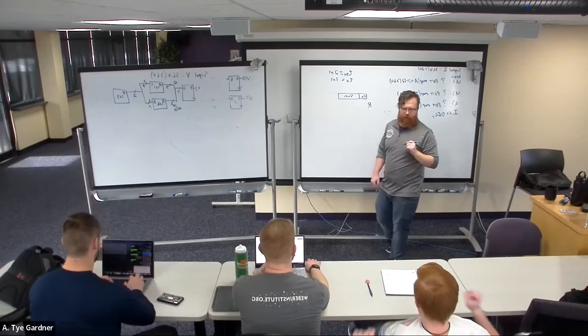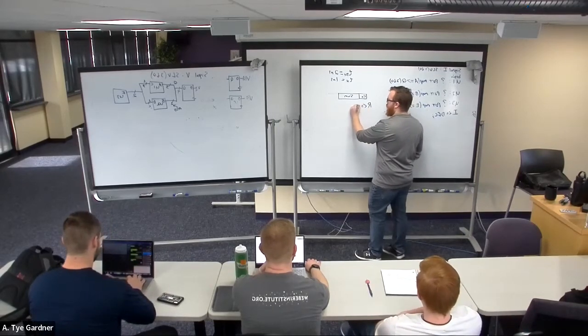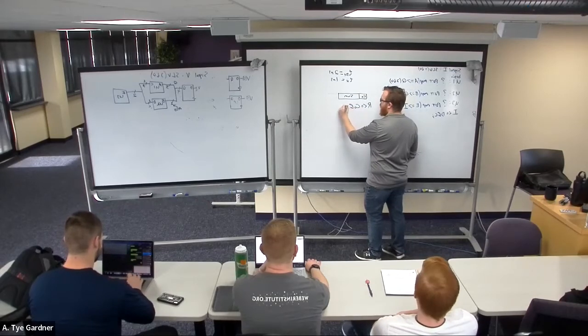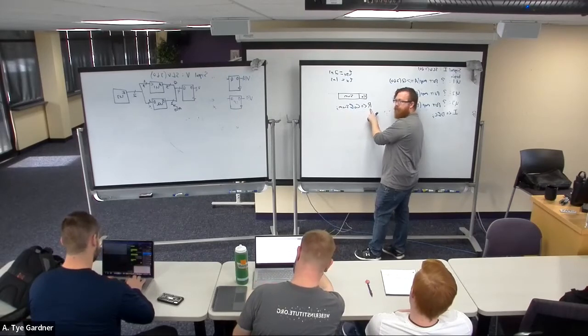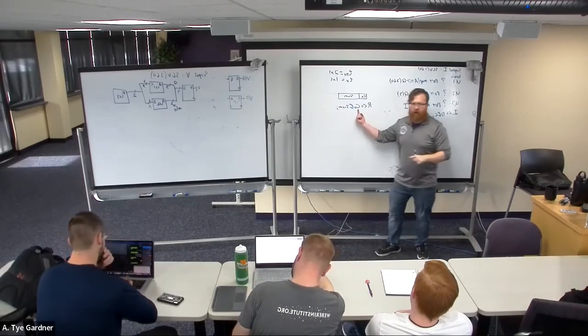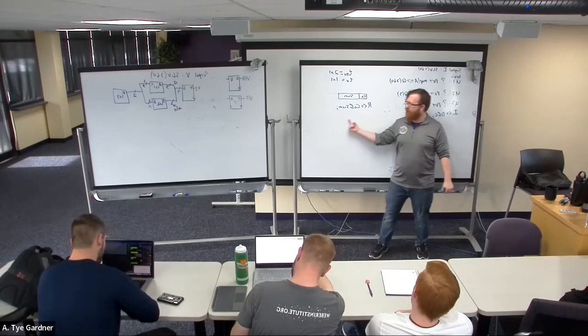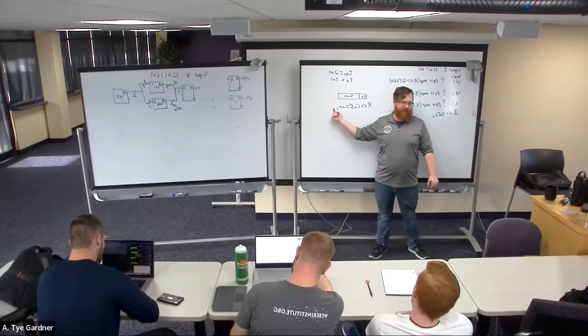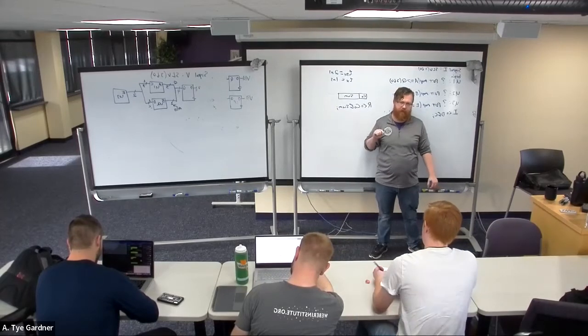We're calling this result, right? And the output of the mux anyways. CO and sum. So if this is 8 bits, this is 1 bit. This will be 9 bits. And CO will be in the biggest position, the leftmost position. If CO is on the other side, it's in the wrong spot because it's now the least significant bit, the LSB, instead of the MSB. So be careful with the order of your concatenation.